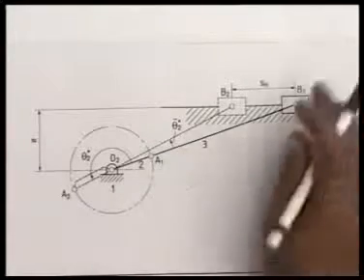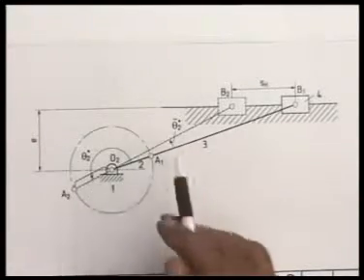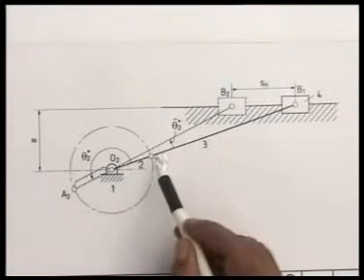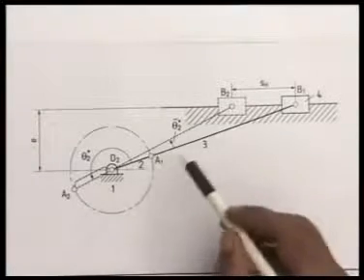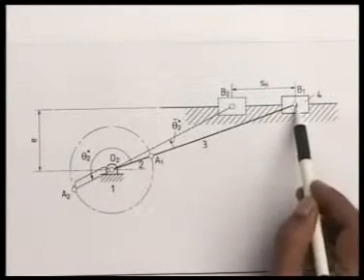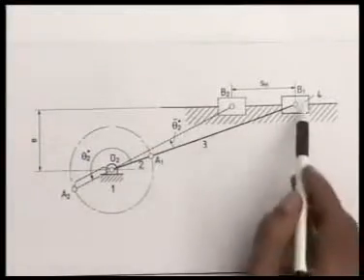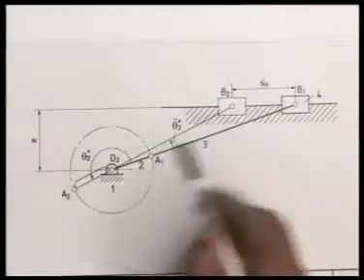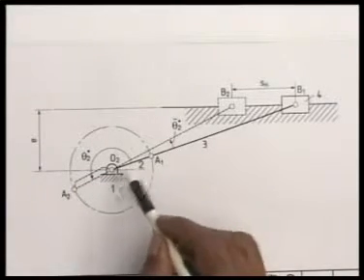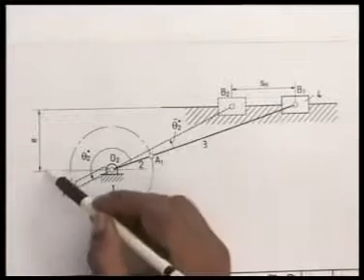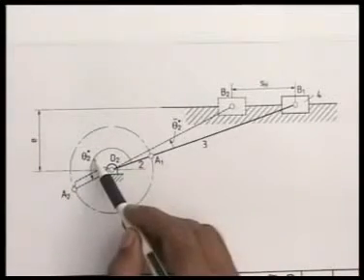So, what is given to us is the stroke length SH and theta 2 star, and we have to come up with the required dimensions of the slider crank, namely the crank length L2, the connecting rod length L3, and the offset, that is the distance between the crankshaft and the line of movement of the slider, as E. So, there are three kinematic dimensions, namely O2A1, A1B1 and E. Given to us is SH and theta 2 star.